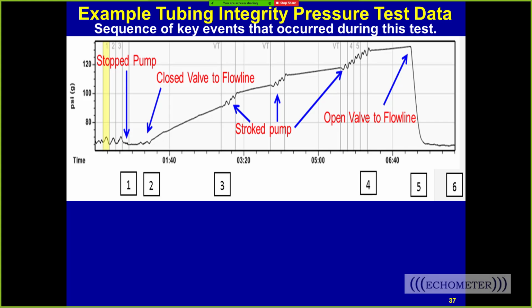I don't know how to exactly answer your question, because each stuffing box has a certain pressure rating, and you shouldn't exceed that pressure rating. If you have gassy wells, you need to look into purchasing or installing a stuffing box that can withstand high back pressure, or you'll be out there on your well every 2 or 3 days loading the tubing back up with water to try to get the well pumping again.